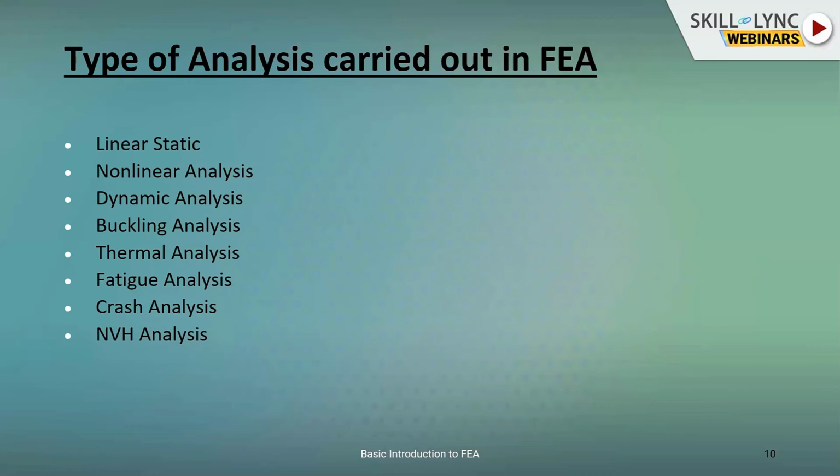The types of simulations we perform are modal simulation and frequency response simulation. We also study different types of vibrations in dynamic analysis. Then buckling analysis is one. Thermal analysis is where we want to find the stresses occurring in the component when the temperature is changing. What is the effect of temperature changes on the stresses?